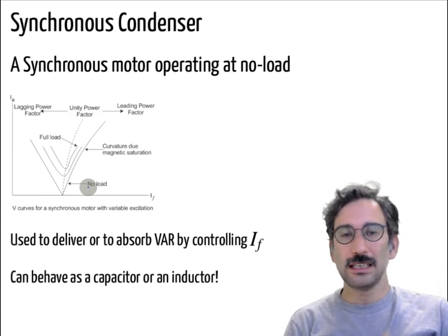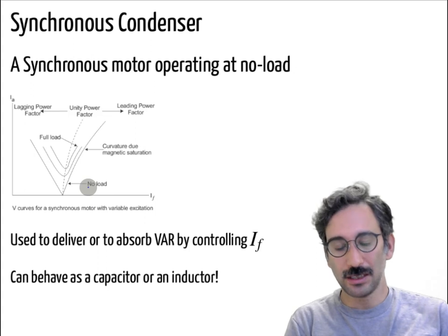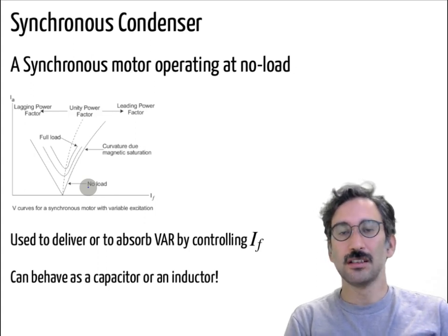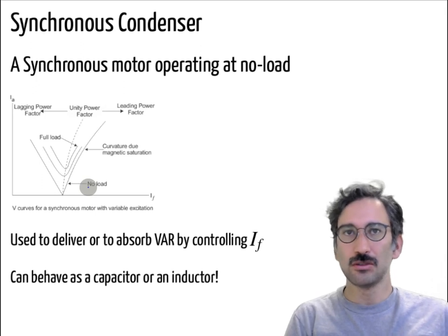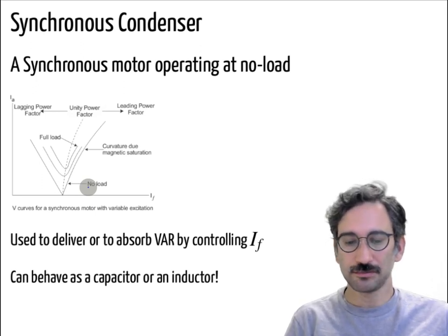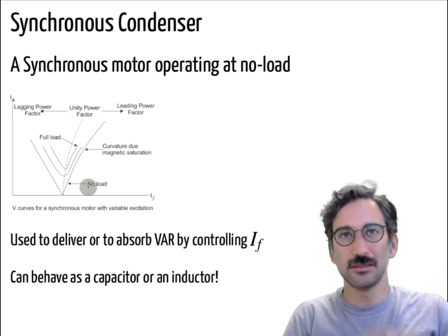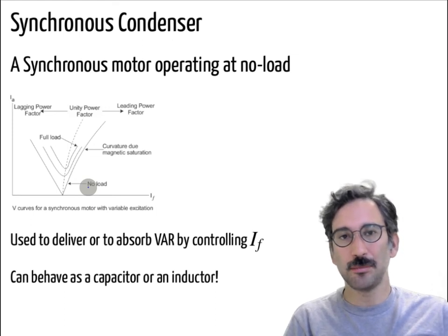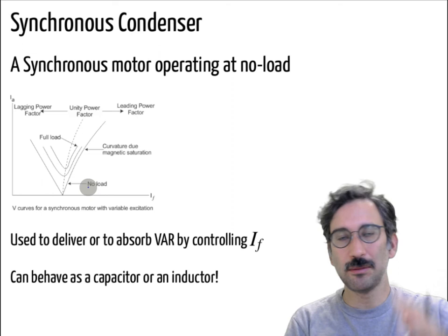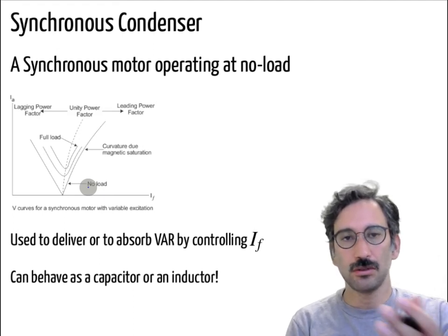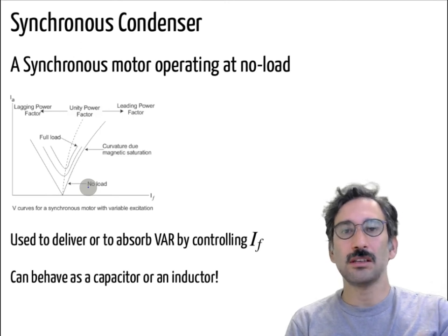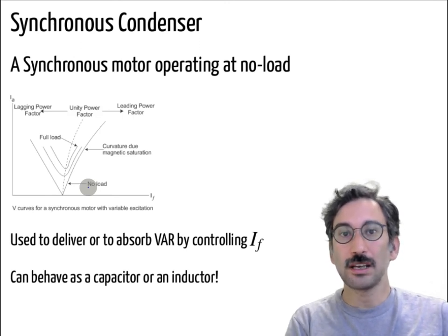In the power grid, they give you penalties if your power factor is too low, whether leading or lagging. Maybe you did your summer practice in a factory like that. There are some compensation systems. Mostly they are capacitors, so you can control the amount of parallel connected capacitors in a system to make the power factor closer to unity. You can do it using capacitors, or you can use synchronous motors working as a capacitor.